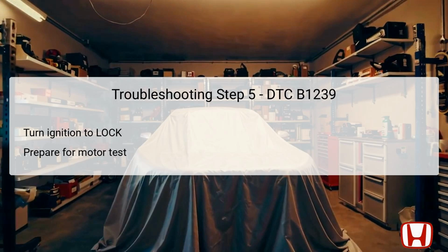and evaluated. This step is foundational before physical checks, as working with electrical components requires utmost care and adherence to safety protocols to prevent any damage to the car or injury to individuals. In this critical step, technicians must test the front mode control motor to determine its operational status. This involves carefully following the manufacturer's specified testing guidelines, which typically include verifying that the motor receives the correct voltage and observing its response when prompted by the climate control unit.